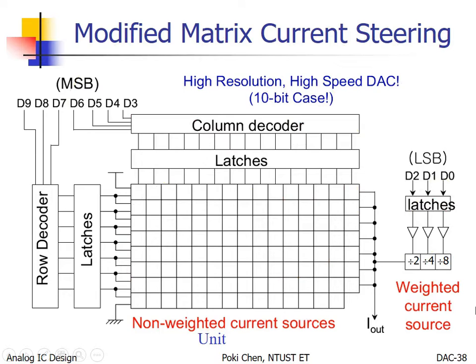Finally, I need to warn you again. Last week, I told you, if you do the layout in practice, just like this, you have the first, the second, and so on. According to systematic mismatch, if I am larger than average, then my neighbors will also more likely be larger than average. So it means what?